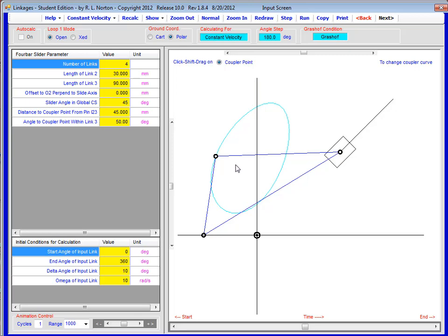And then you can just use MathCAD to make the calculation. That's what I would suggest that you do. It's easy to sketch this out in SolidWorks, and then you can extend these lines so that you can find the instantaneous center and use driven dimensions, and that way you can get all the information that you need to use the method of instantaneous center. You should be able to do that fairly quickly. So anyways, this gives you an idea of how to set this up, get the plot, and then do the calculations using the method of instantaneous centers and compare your results to the plots that you got at the particular angle of the crank.